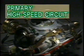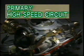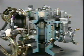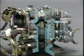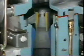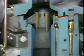Next is the primary high-speed circuit. The construction of this is similar to that in the carburetor model we looked at earlier. It is the most widely used main circuit, although there are mechanisms to activate to assist when extra power or speed is needed. This side is the primary barrel on this model. The Venturi is designed this way for maximum mixing of air and fuel.